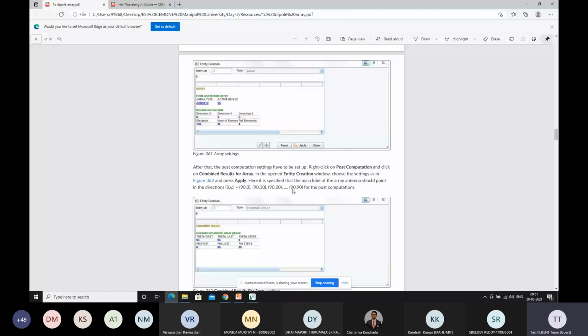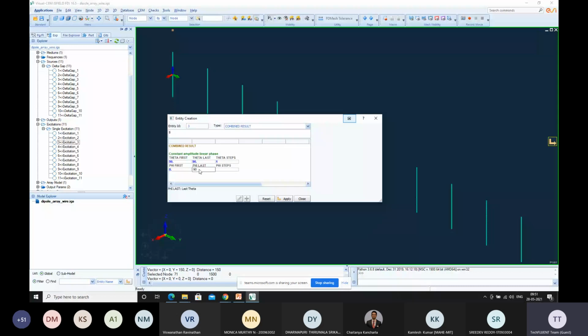And it's always a best practice to reduce your coverage also. I mean, if you want to see your result coverage between this particular small range, it's computed very fast. If you want to go ahead with the complete range, it takes a lot of time to compute. So theta directly we are taking 90 degrees, exactly 90 degrees we'll be getting the response. And phi you can go ahead with 0 degrees to 90 degrees with 10 degrees of step.